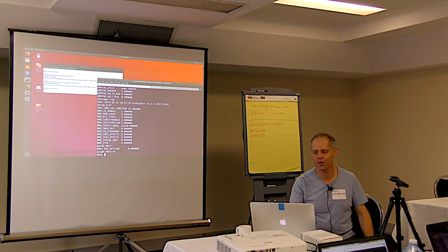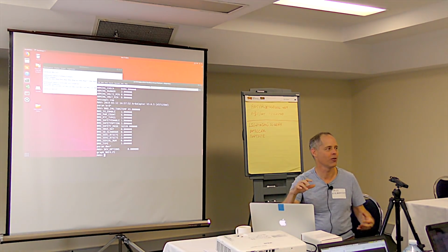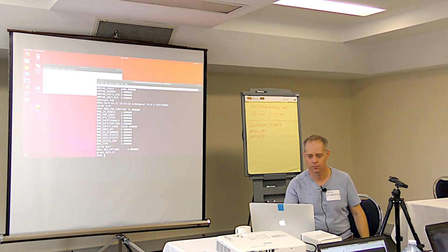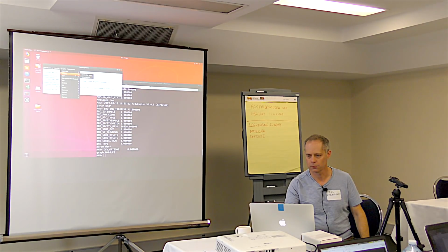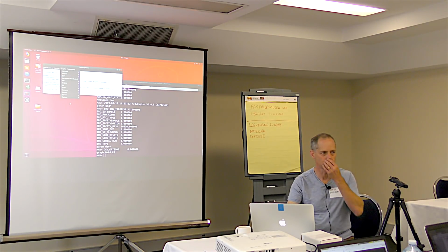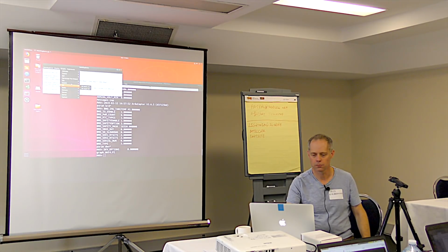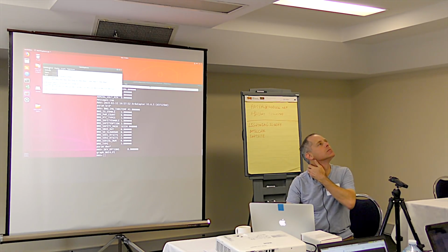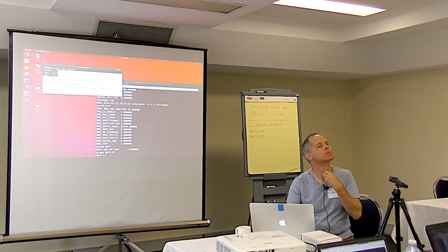What it does point out, though, is that it's a good example of a lane switching event, and it's a great example of a very high level of magnetometer interference. We're going to get it more often as we start having CAN IMUs, assuming we decide to use them. If we start doing CAN IMUs, it's going to be more common for people to do it. Should we add the ability to actually force it to change lanes so that it can be tested on the ground? Or should we do a startup where we actually change lanes to verify?